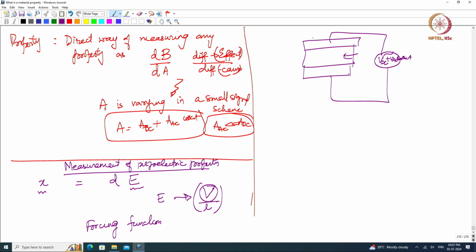I should measure the displacement of this membrane, right. So, I am applying field in this direction. So, if this is my direction 3, E is applied in direction 3. And I am going to measure the vibration of this, right. So, the displacement up and down, right, of this membrane or of this material, and so what I am going to measure is the displacement. Now, I have already used D for D33. So, for displacement I am going to use delta, right. So, I am going to measure delta 3.